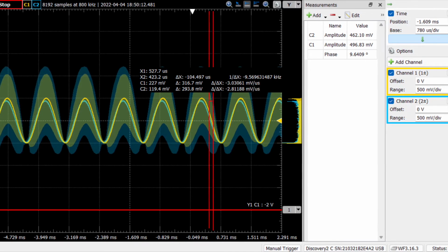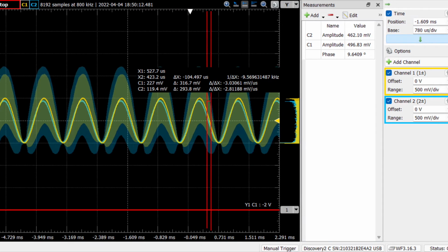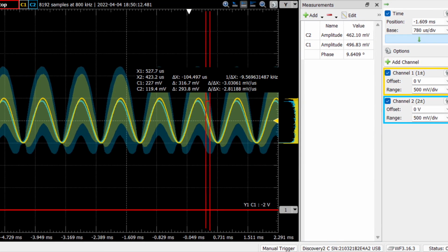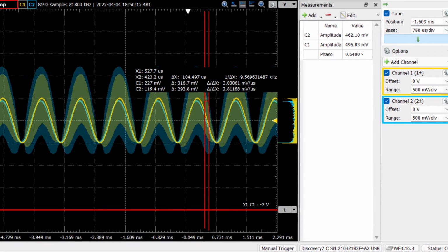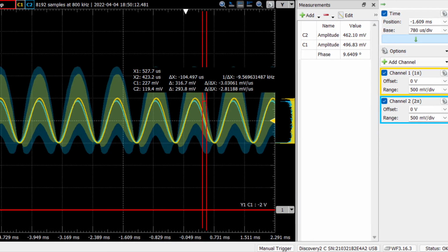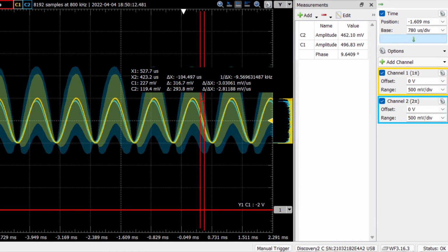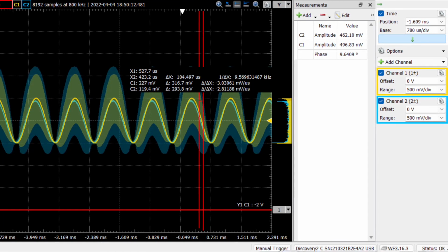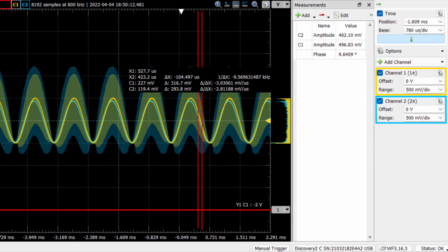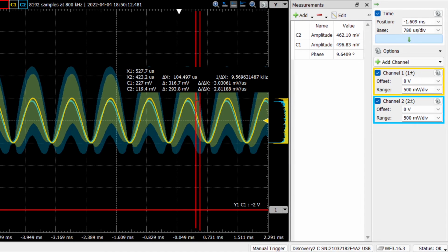To set up this simulation, I also used WaveGen and supplies. WaveGen was used to set up the amplitude of the wave, and the supplies was used to set the voltages of the top and the bottom volts. So they would give in a positive supply of 5 volts, and it would also give in a negative supply of negative 5 volts.